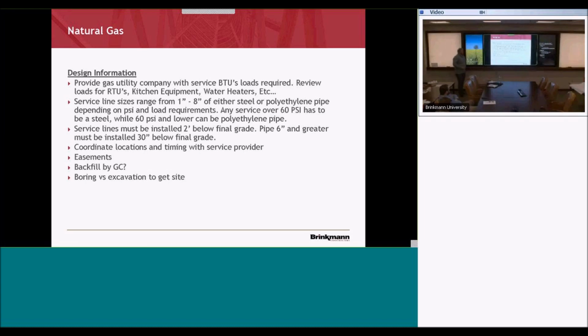If you've got gas available, then it's usually cheaper for the owner to run the building. If you don't have gas available, you can get with Fleet Gas. They'll give you a map of where it's closest, and they'll let you know if they'll run it to your building for free or not. I know right across the road, the bank didn't have a gas main running there. The closest one was at the Taubman outlet mall, so they had to come 450 yards down the easement of the road, and then they'll branch off from there and go into our site.